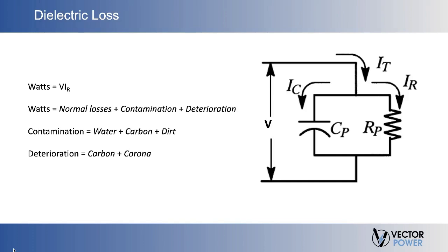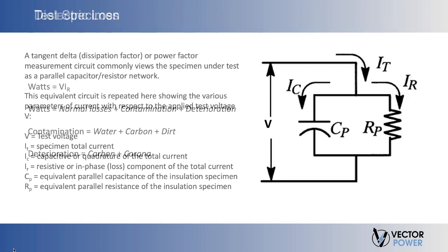Again, for example, heat. It can also be parameterized in terms of either the loss angle, delta, or the corresponding loss tangent of the angle delta. Both refer to the phasor in the complex plane whose real and imaginary parts are the resistive, or the loss, component of the electromagnetic field and its reactive, the lossless, counterpart.